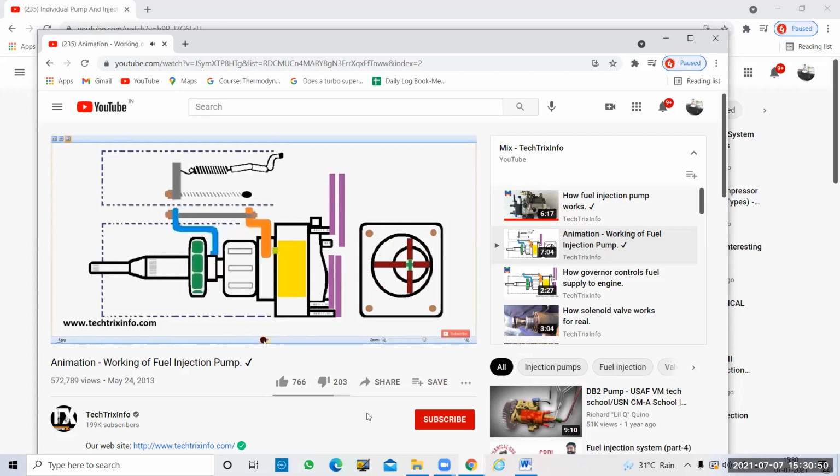You can see this metering valve is also rotating, and this particular lever, which is in blue, is also moving because the governor weight retainer is pushing it, and it is connected through this ash colored spring towards the metering valve. The metering valve has an internal gallery, the green one, connected towards our rotor pump or the vane pump. This yellow is showing the internal view of the vane pump, which is over here. The vane pump is actually supplying the fuel as it rotates.